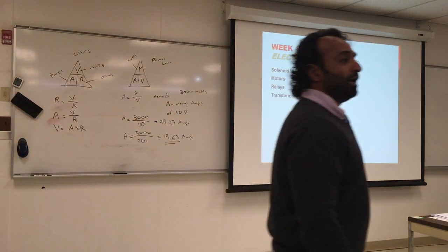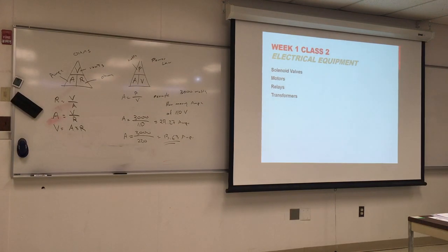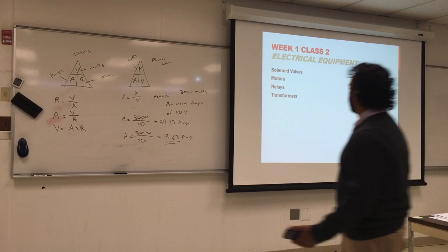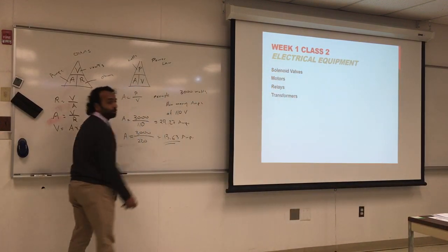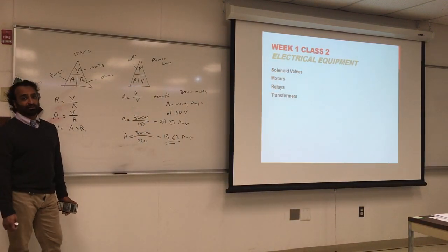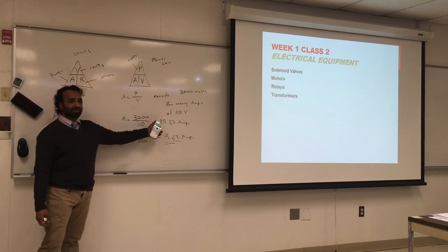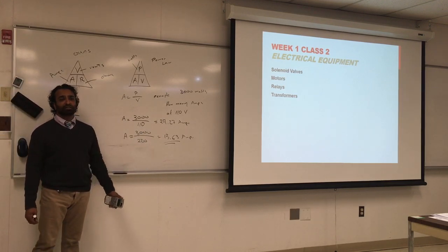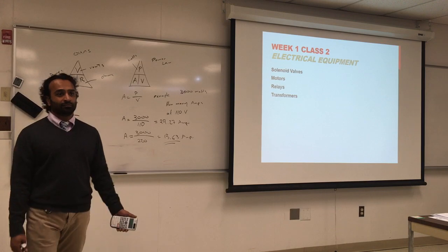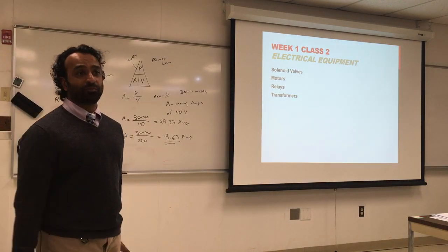And that's why in Europe and South America, some countries are different, but everybody uses 220. We are the only ones who commonly use 110 for all appliances. That's why on your phone charger you'll see it's between 110 and 220. We try to accommodate more countries. So I'm going to lower the load in the circuit, which is better. Instead of drawing 27, I'm going to draw 13 amps. The circuit is going to be cooler. The wire could be smaller.